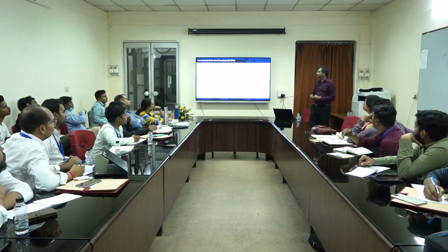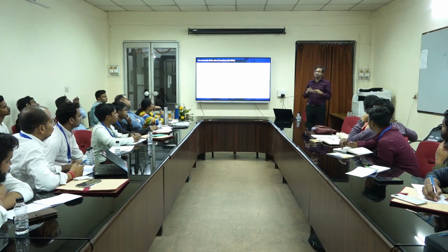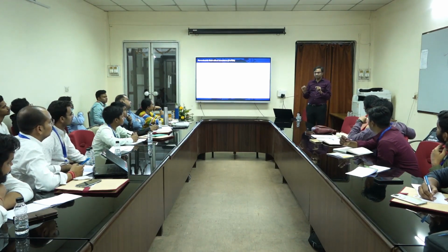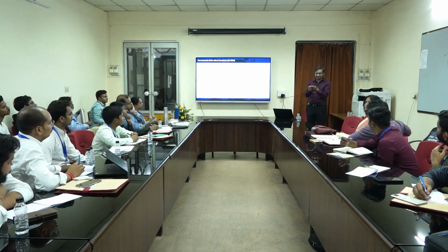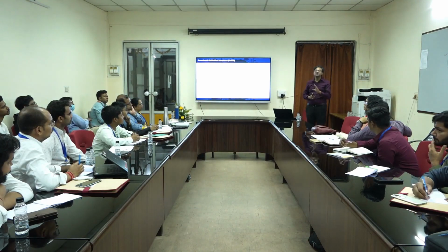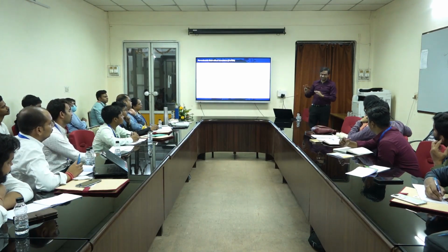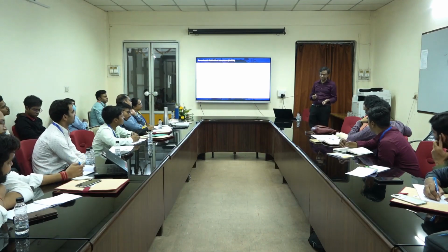So I think maybe I will talk to you about the previous lecture, because we are talking about 2 different devices. For a transistor, I need a thin channel, and that is where I want to use my monolayer MoS2. You are talking about a memristor device. There I don't think there is a requirement that it has to be a monolayer. You can actually do multiple layers because it's a 2-terminal vertical device. Right? There is no scaling law, there is no Moore's law for memristors, right? And it does a different function altogether. So therefore, I think the requirement is very application specific, right?